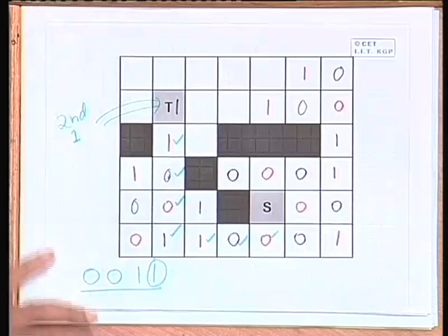There are a few other heuristics which are used to improve the running time of Lee's algorithm. What we have talked about so far is with respect to memory, where the number of cells you have to label can grow very large. But the execution time will depend on how many cells we have to label during the breadth first search scheme. So, if we can reduce that by some means, then the execution time will be faster.